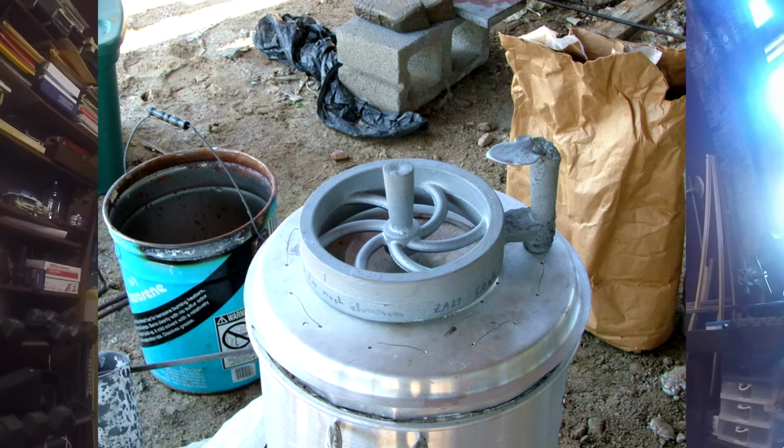Anyway, so risers. Here you have a casting. The outer wall, the ring out there, is uniform. The spokes going in towards the center are uniform. But something that's not quite the same as everything else is that central hub where the shaft would go through. Now it's obvious that if you have a thicker part in amongst a bunch of uniform parts, that part is going to be the part that shrinks. And they put an open riser on top of that to feed that.